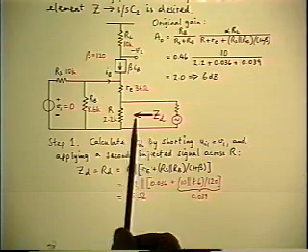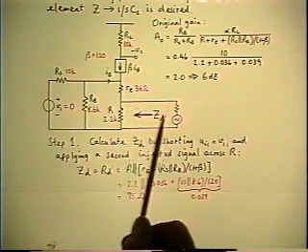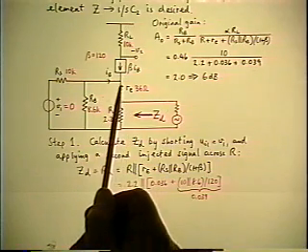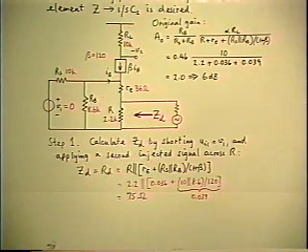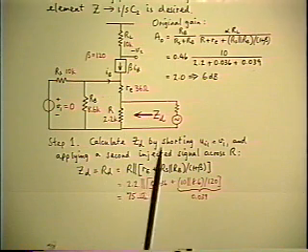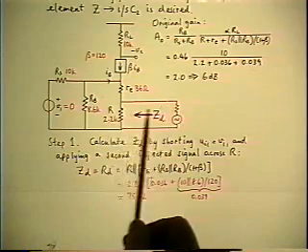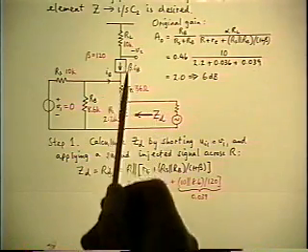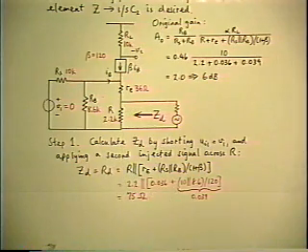So what that tells you is that the dominant component of the driving point impedance ZD is the path through RE. The path through R is almost negligible. In other words, most of the current that is being driven in from the second source, most of it's going into RE, hardly any of it's going into R. Okay, well, conceptually, there was nothing new about that.